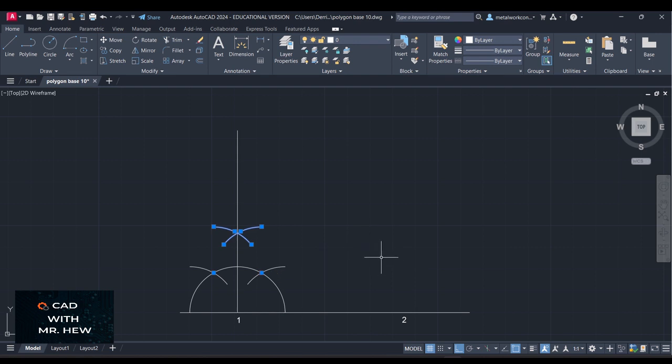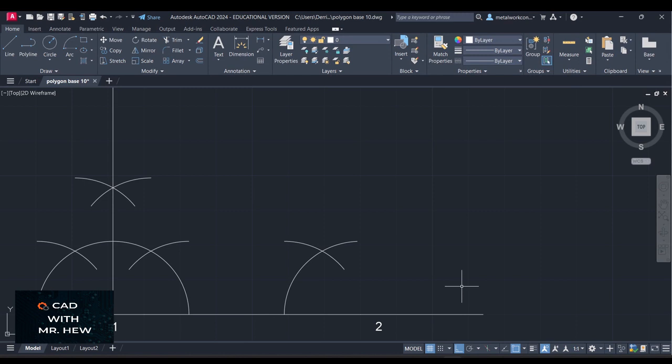What we're going to do next, we're going to construct a 60-degree angle at 2. As we indicated, we'll be constructing a 60-degree angle at 2, at the end of the line 2. So what we do, we put our compass point at 2. If we're using the traditional instruments, that would be the compass. You scribe an arc, any radius.